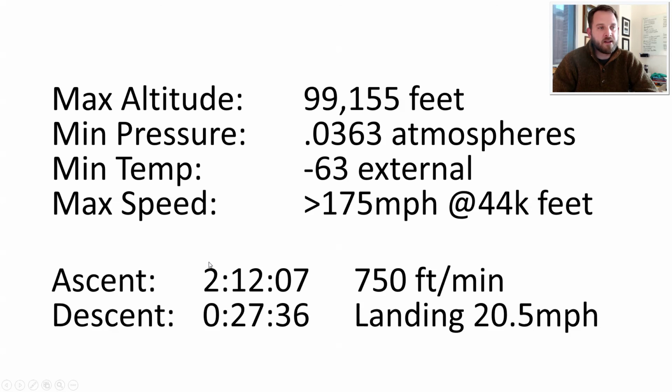The ascent rate was 750 feet a minute. It took us 2 hours and 12 minutes to get to burst. When the balloon burst, it only took us 27 minutes and 36 seconds to get back to the ground, with a final landing speed of about 20.5 miles an hour. So you could throw the payload at the ground harder than it actually hit the ground.